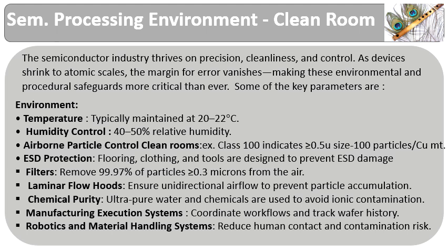Static electrical charge damage is prevented by employing features like specialized flooring, protective operator garments and tools, robots for material movement, etc. A high-efficiency particulate air filtering system is employed, that filters 99.97% of particles greater than or equal to 0.3 micrometers, and thereby ensures ultra-clean air.